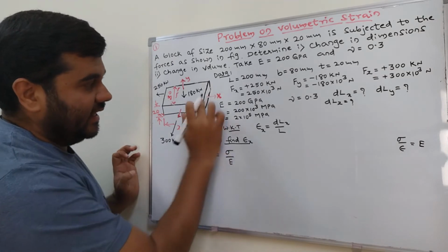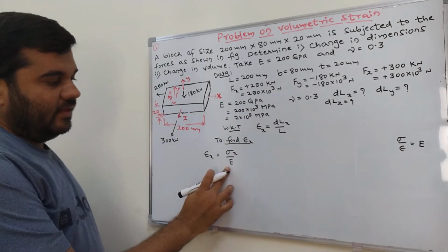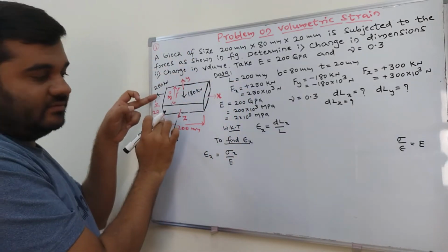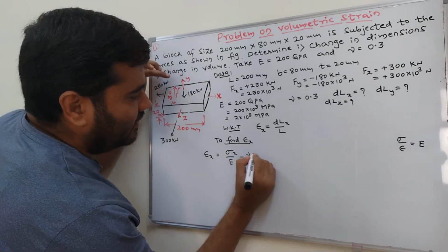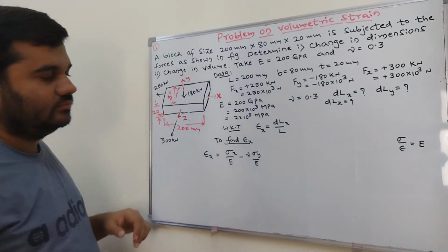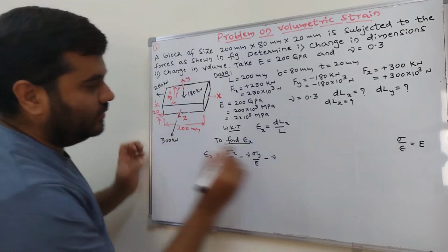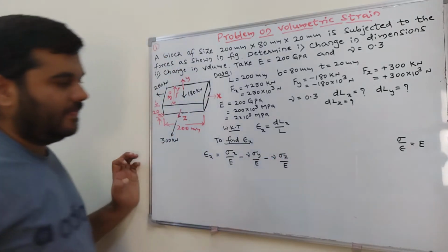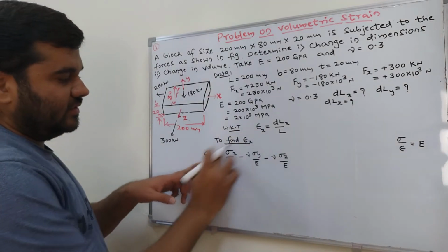What? Stress in x direction divided by E. This is related to this. It also affects y and z direction. Minus nu into stress in y direction divided by E, minus nu into stress in z direction divided by E here. Okay, to find out strain in x direction.